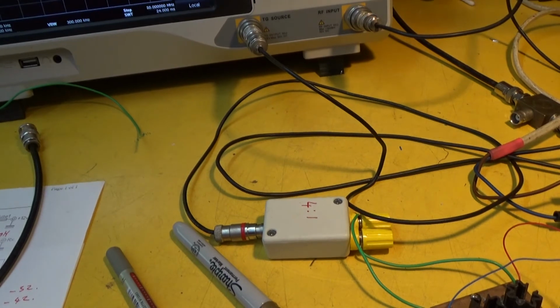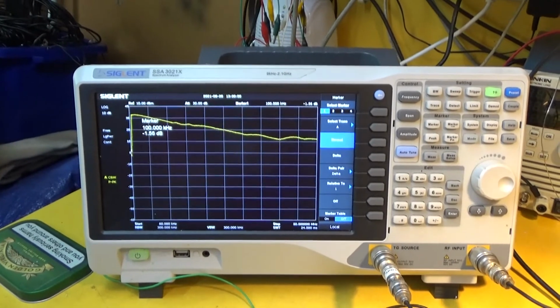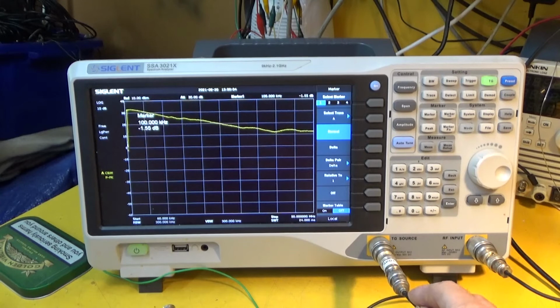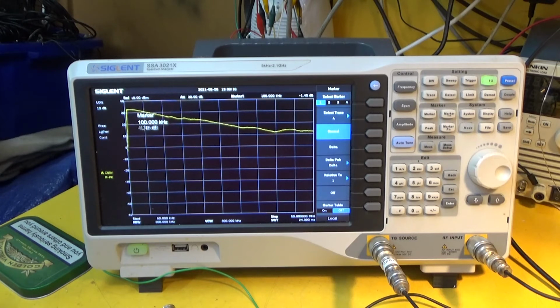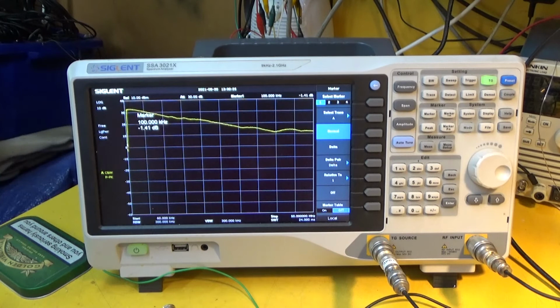And my system over here, I'm using the tracking generator output as a signal that goes into the balun, and the tracking generator I don't think starts below 100 kilohertz, so in other words it will only output a signal at 100 kilohertz up to the 2.1 gigahertz top frequency of the spectrum analyzer.